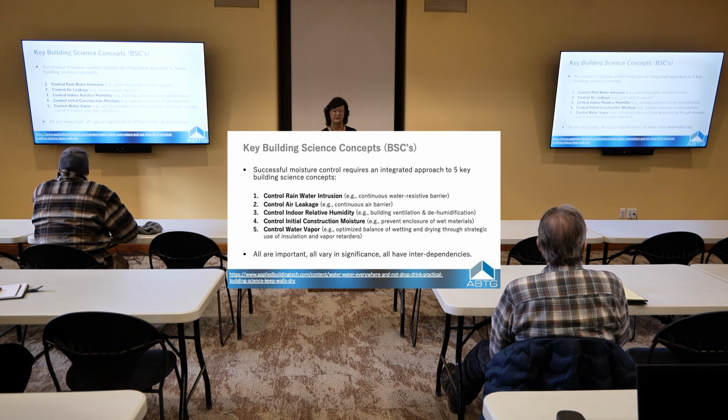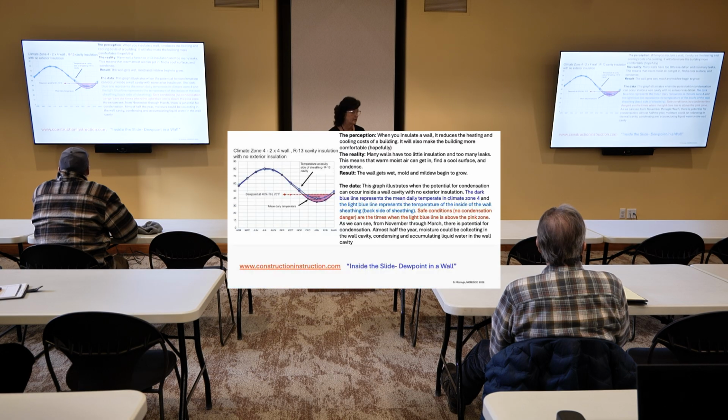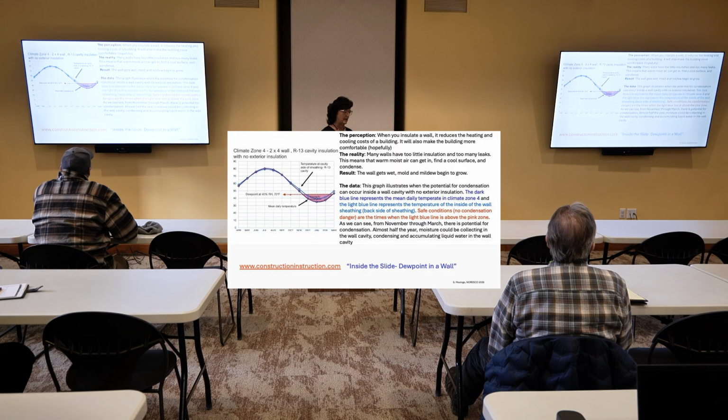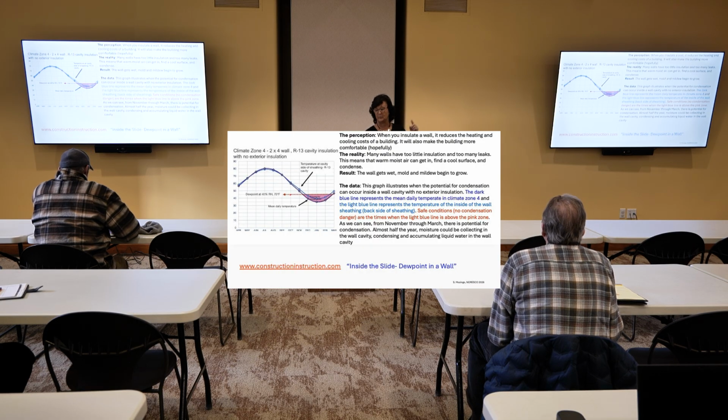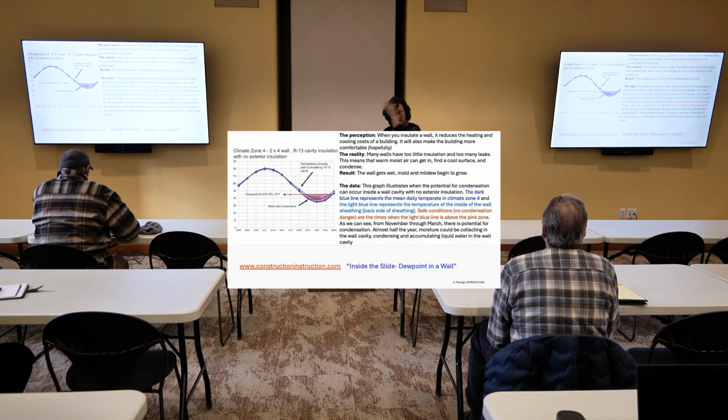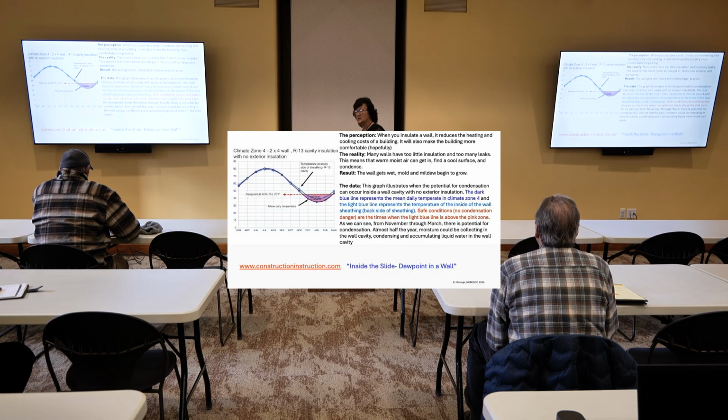How do we deal with water vapor? If you haven't seen dew point calculators, you need to, right? We need to be checking those out because of the way that we're building. We need to make sure that we're keeping that dew point away from the sheathing, right?